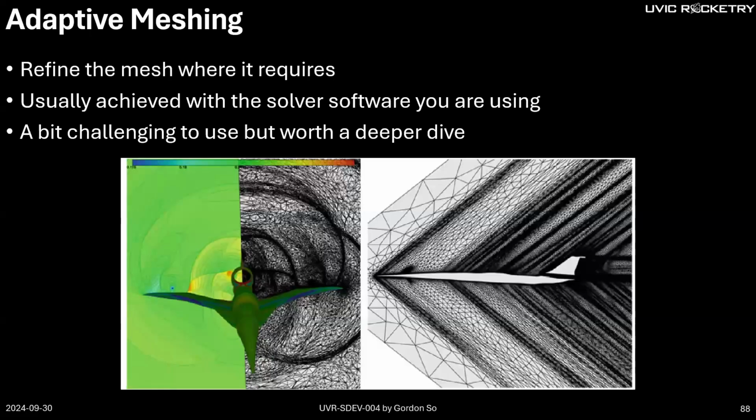So this is something that you will see in adaptive meshing. You see all the shock waves, it would refine really fine because you want to capture those changes. It's a drastic change. And anything that has gradual change, not much change, doesn't have as much mesh. And this is good because you save mesh, and you save RAM, which we may talk about today because it's a fun topic. To close out this part 1.